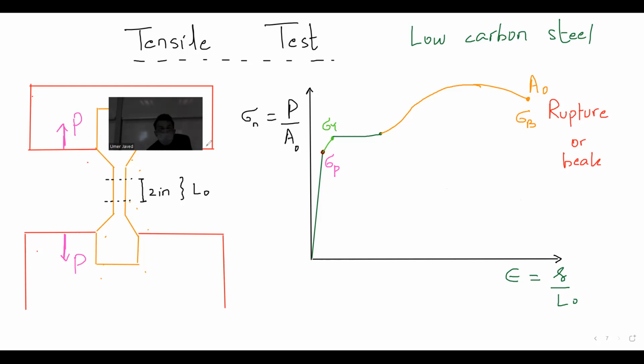This is the elastic limit. Anyone who wants to point out which is the elastic limit? The linear part. But wait, even from here till this point it will come back, right? Even from a little before that, from here it will come back if I remove the stress, right?